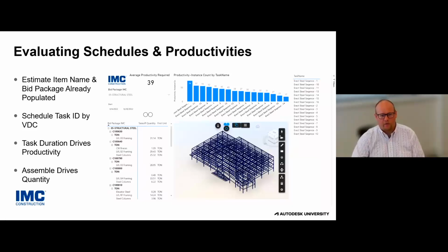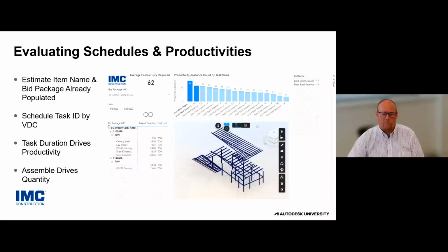So if you click, you'll start to see now with the dashboard, with the connected data, we can start to drill down on any individual sequence and understand, all right, maybe this is right. Maybe we do need a longer duration for this rather than just assuming the same duration and seeing a higher productivity. So if you look at these two sequences of structural steel, one obviously has columns, which take longer to set. One has a canopy, which is a lot of pieces in a small condensed area. It's going to take a while to set.